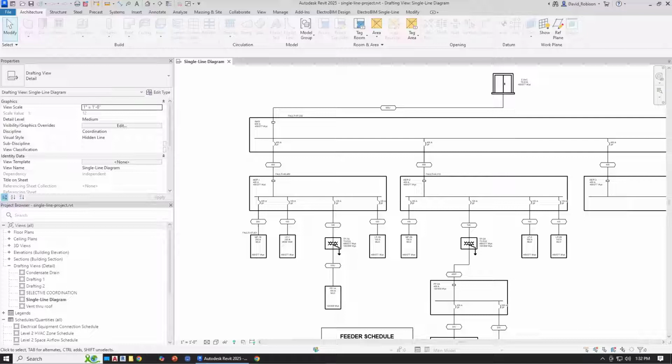We actually don't do the sizing on that, and we will come back to how you handle that at the end of this training. So we'll come back to 250-66. Otherwise, we have 250-122, which is for equipment grounds, and 250-102, which is for service grounds. And we do sizing for that. And these are the grounds that are going to be in your feeders or your branch circuits.